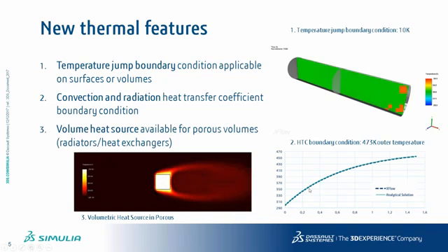Of course, that's a simple simulation. It's actually a sort of a cube, but you can see that the law is correctly applied, and this boundary condition can be applied in a way to not actually solve the environment around the geometry you are interested in, but to mimic that effect as a convection radiation parallel system.